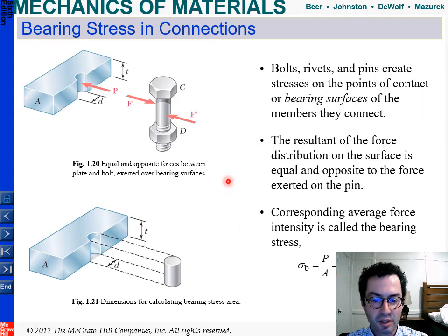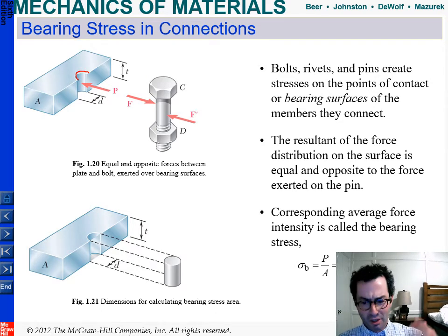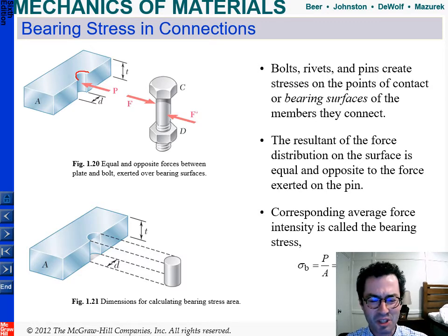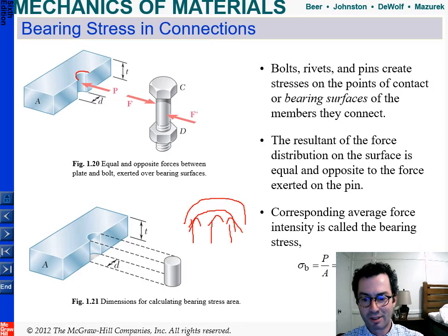And this is covered up a little bit, but your bearing stress is equal to your total force over your area. What's kind of interesting to me is that when I was first tempted to look at a surface like this, I'd see the surface of the bearing and want to say we'd have to do the force over the whole area, but that's not actually how it works. When you've got a force on a semicircle like that, the force is still always pointing directly in this direction, from the bolt. The bolt also has a semicircular area.